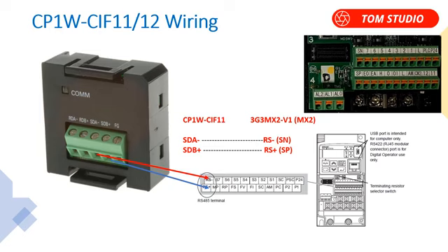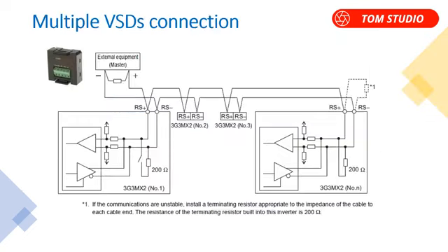As you might have known, RS485 serial communications only needs 2 wires to implement the communications. Only RS422 needs 4 wires. Of course, if you want, you can definitely connect multiple devices on the same serial communications. For example, if you want to connect 4 or 5 VSDs, that is definitely fine, but don't go for too many devices like 10 or 20. The challenge is serial communication speed and the PLC's memory limitation, please be aware of it.